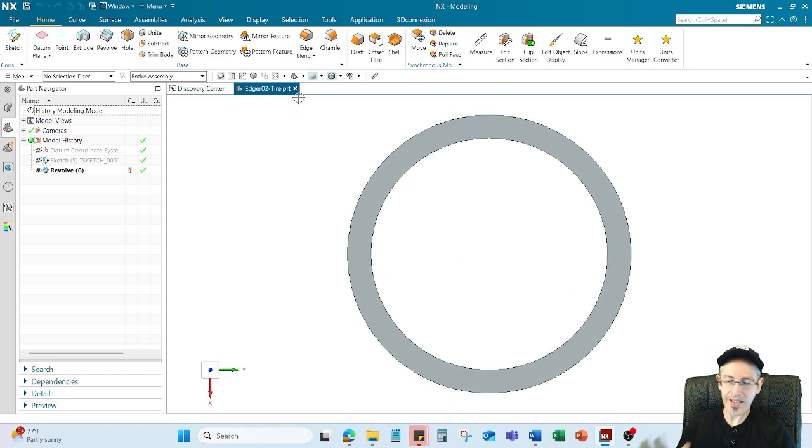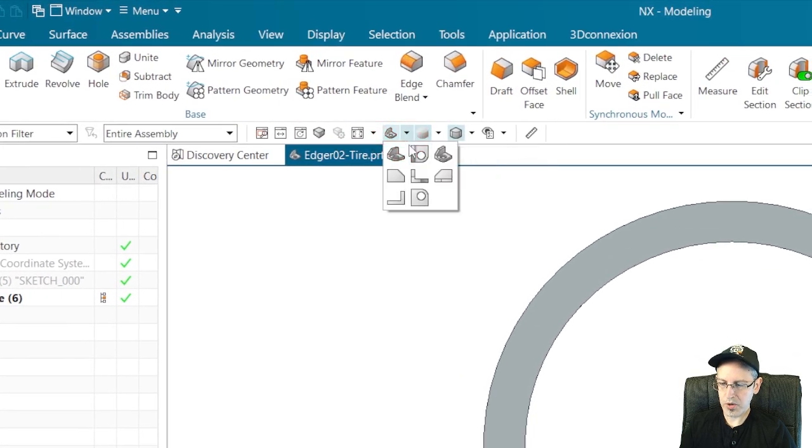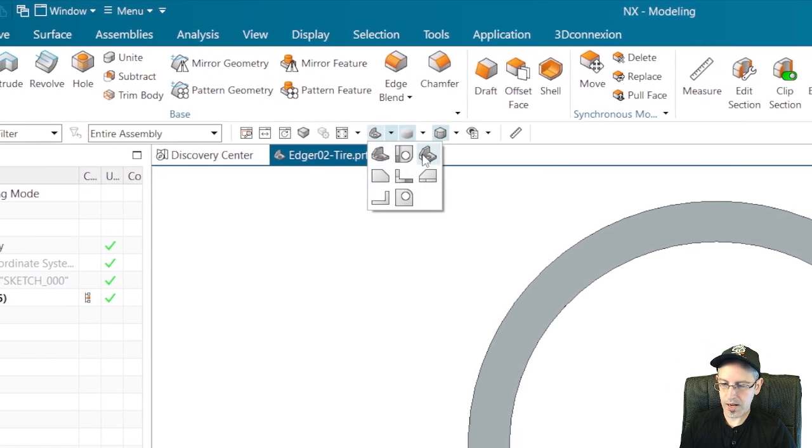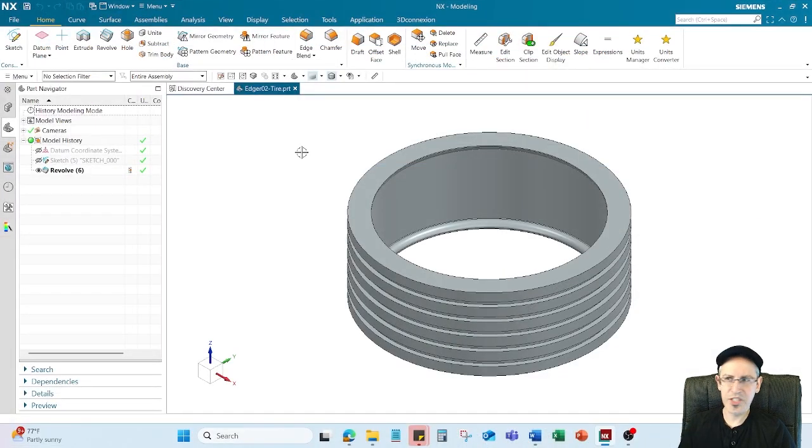But yeah, let's just make an isometric view for now. So if you go over here, there's a little drop down menu and you have a bunch of different views you can use here. Let's just click on isometric. It just positions it nicely. That way you can see all the different facets of this model, the inside, the sides. A lot of drawings that engineers do, they'll always have an isometric view to show all the different kind of angles of this part. Let's now click on save so we can save our work.